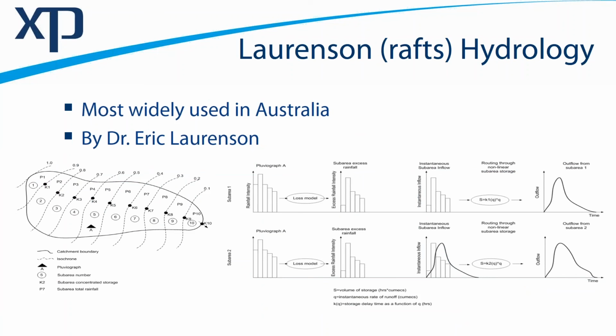it has an equation which is S equals BQ to the n plus 1, where S is storage, B is a coefficient that comprises area and the fraction impervious, and also the catchment slope. So it wraps all of those parameters in. It's a bit of a complicated process. Thankfully, the software looks after us to do this quickly, and ultimately we will generate a hydrograph very quickly at the back end.